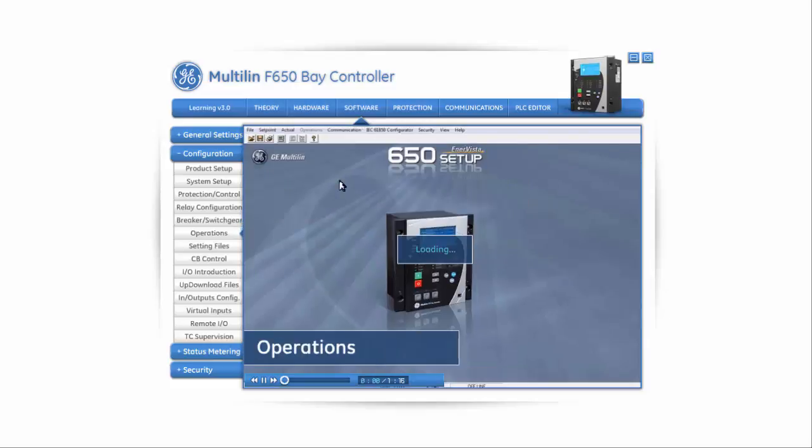As mentioned before, the F650 is a complete bay controller and protection relay. As such, the F650 relay can be programmed to perform up to 24 different operations, which can be executed from the HMI front plate or from the software. The relay allows the possibility of choosing whether to execute all the operations locally, remotely, or by a push button in the front plate. The operations can even be configured to be operated via the graphical mimic display if your relay has the graphic front plate option.